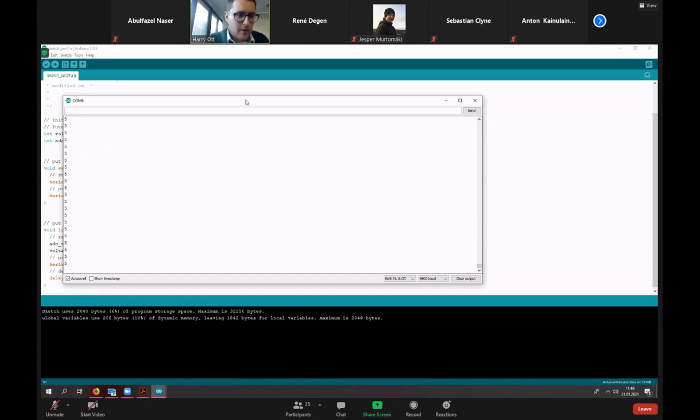But the problem here is that we have a resolution of 10 bits, but we have made some mistakes. We have chosen the wrong data type for this voltage. We use integer, so we are not able to plot floating points or numbers with decimal digits.